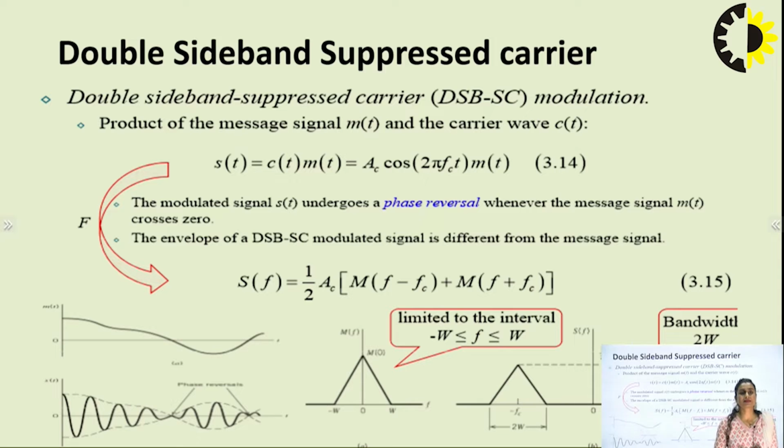As in the previous lectures we have seen that, for a perfect modulation case, 2/3 of the total power gets wasted in transmitting the carrier only. So in order to save that power, after performing modulation, we may suppress the carrier amplitude so that what we transmit consists of the necessary information, and the power wastage because of the carrier amplitude is suppressed and could be saved.